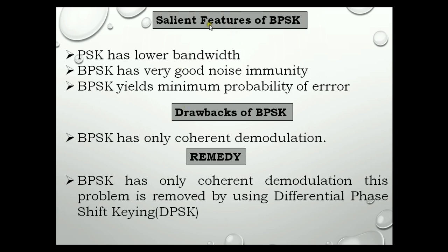BPSK has various salient features, that is, it has a lower bandwidth, it has very good noise immunity, it yields minimum probability of error, whereas the drawback of BPSK signal is it can have only coherent demodulation. In order to overcome this drawback, we go for differential phase shift keying.